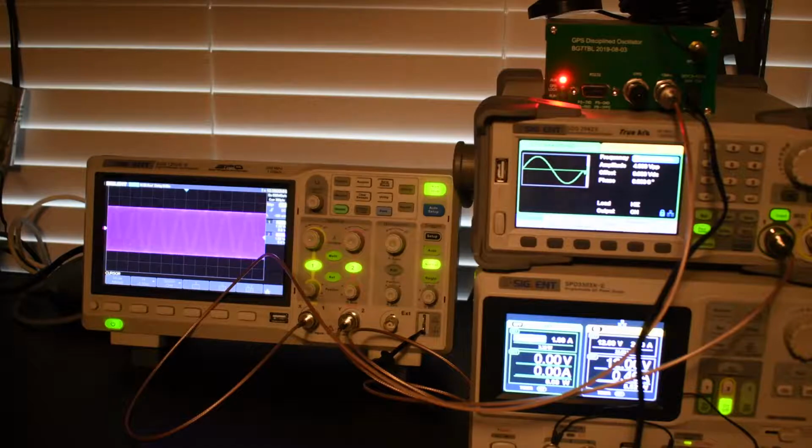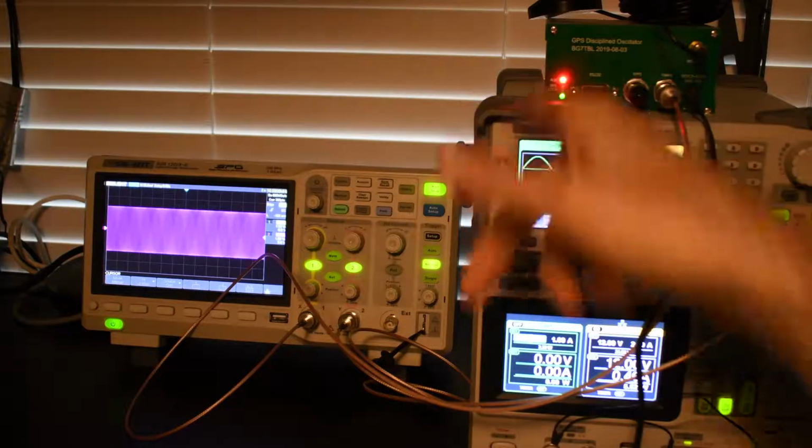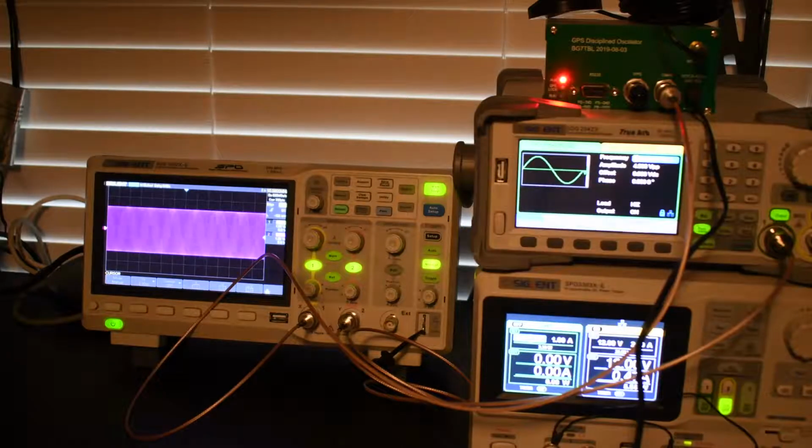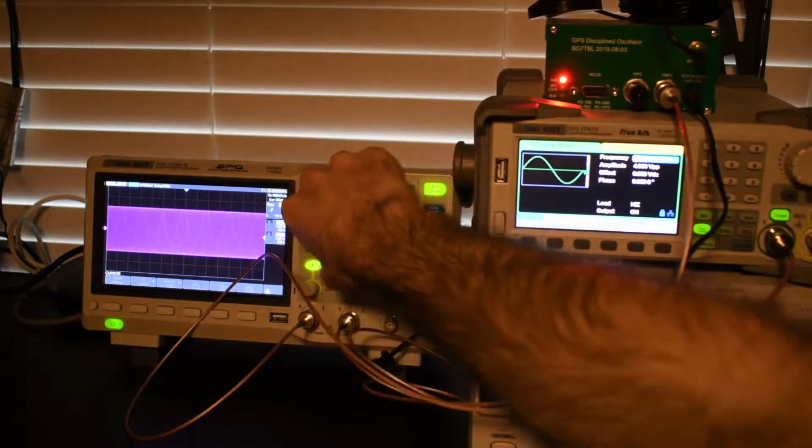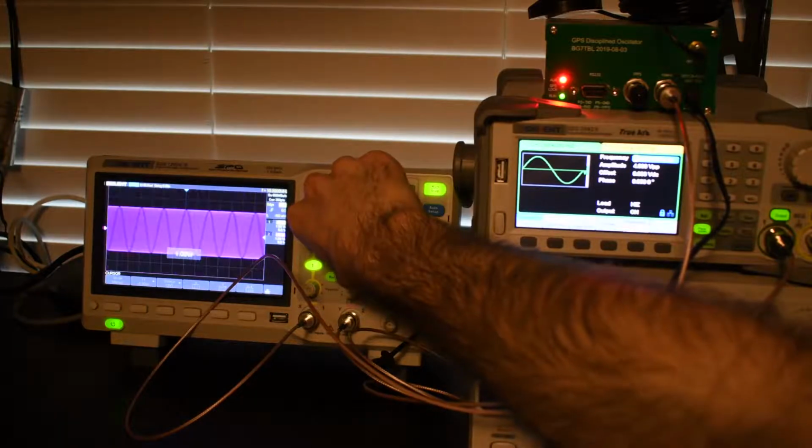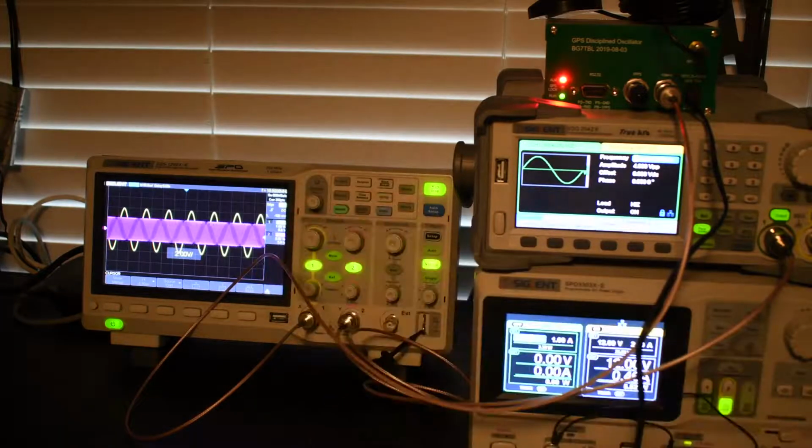So you can see already that these are both nominally 10 megahertz, and it doesn't have a lock on the GPS yet, so it's not fair, I guess you could say, to evaluate it yet. But right now you can't see channel 1 because channel 2 is in the way, so I'll change the amplitude like that. So those amplitudes are the same, but the scales are different. And you can see how even though they're both nominally 10 megahertz, the frequencies are not just different, but they're varying also a little bit in time.